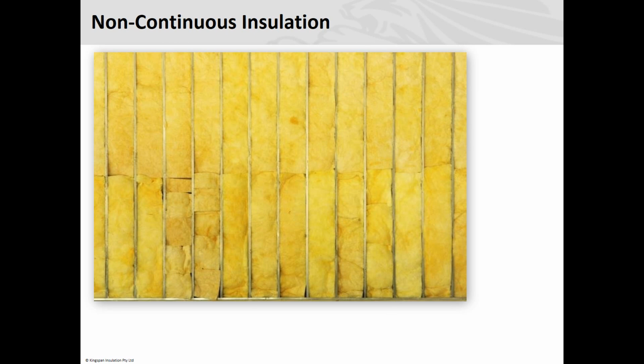But one of the things I say to designers a fair bit is, we manufacture the Insulbreak, which goes underneath your iron roof or your tiled roof, and it's pretty important to have a reflective insulation under your roof, as opposed to just having insulation on top of your ceiling. So you've got your house construction here, and your ceiling here. A lot of people will put an R5 on top of the ceiling, but with the heat gain on a 35-degree day, it will get to 70 degrees temperature in here, quite easily.